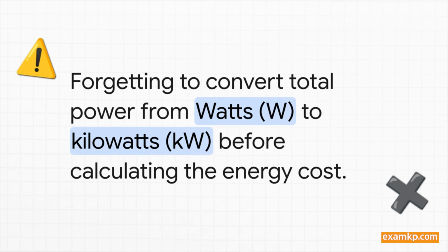The number one mistake people make here, they forget to convert watts to kilowatts. The price is per kilowatt hour, so your power has to be in kilowatts. It's a simple step, but it's so easy to forget in an exam. Don't let that be you.